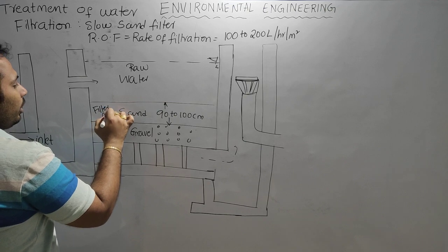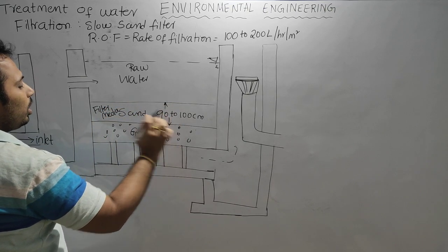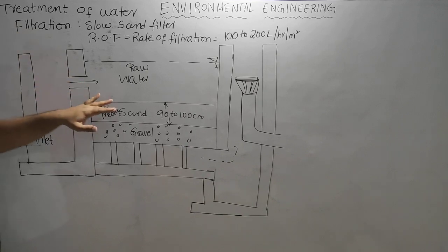The thickness of this filter media is 90 to 100 centimeter, approximately 1 meter. And below this filter media of sand, there is gravel.